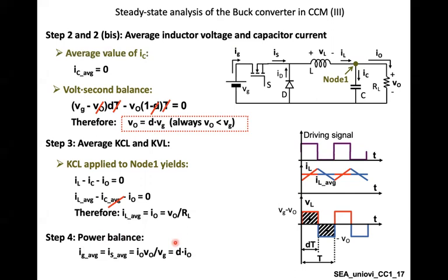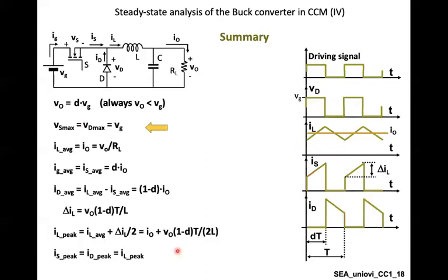And this is the concept of a buck converter. In a buck converter, we step down the voltage by a factor D, and this D is controlled by the duty cycle. Alternatively, we increase the current by the same factor D. A summary of all equations related to the buck converter can be found in this slide, considering all the KVL and KCL we did.